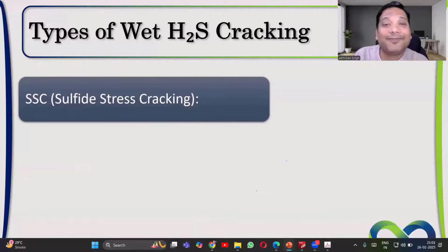So, types of wet H2S cracking. The first one is sulfide stress cracking. I have ignored HIC and SOHIC here. Why? Because SOHIC is very rare, it very rarely happens. And the second thing is, very little development has been done in terms of SOHIC.